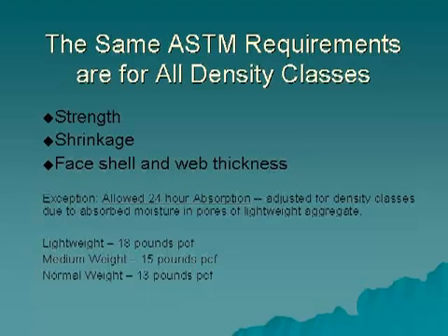So the control number for lightweight density block was increased by 5 pounds for absorbed water, making the limit 18 pounds of water for 1 cubic foot of lightweight concrete. This then served as an equalizer to determine the degree of compaction and interparticle void content for structural grade lightweight block.